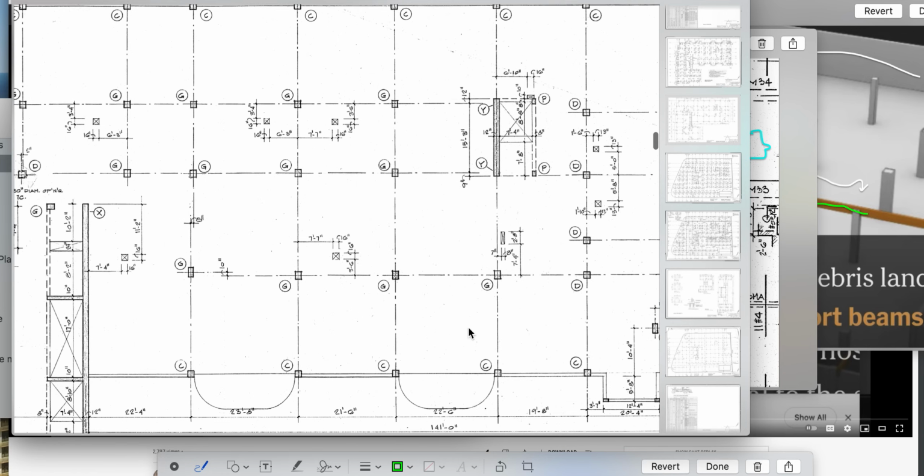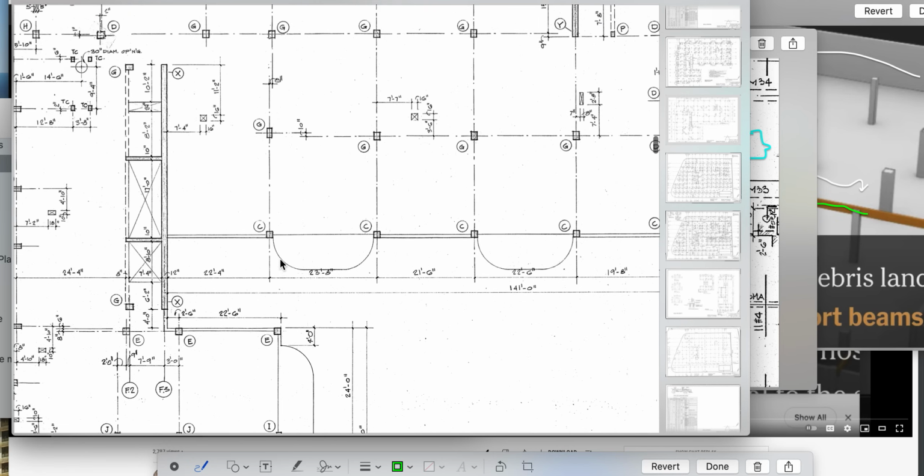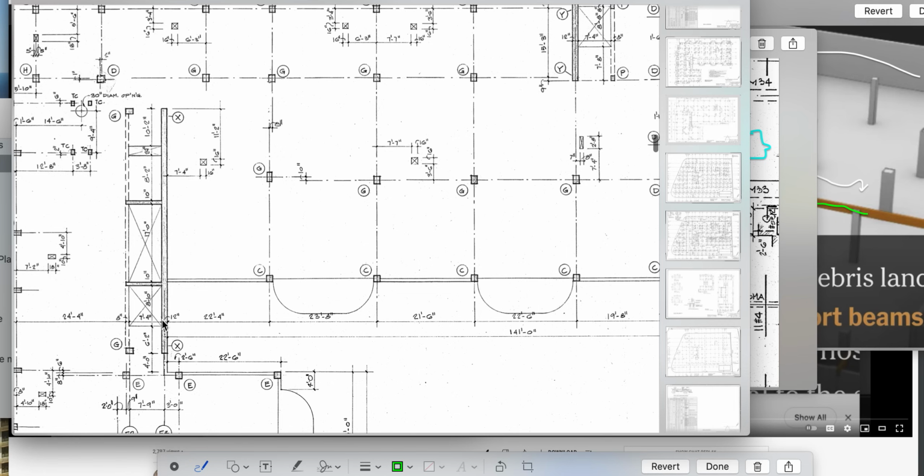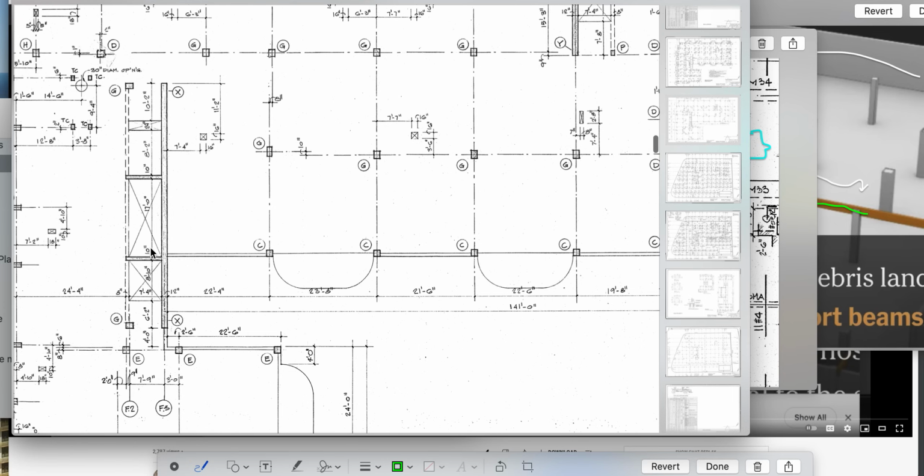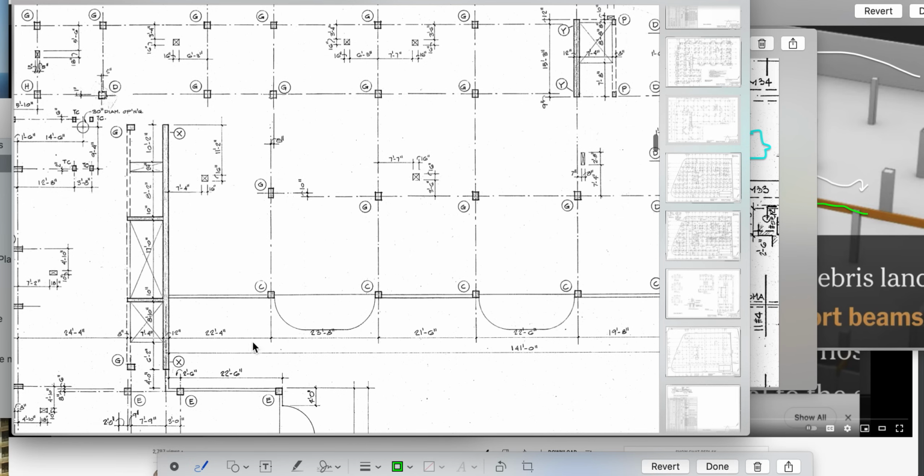M is the shear wall that everyone says doesn't exist. Well, obviously it worked. The problem is the rebar goes across the shear wall via the slabs into the slab next to it. This one worked because there was literally a wall here because the elevators were built up, and so they couldn't go through the elevators. At some point they do go around, and the stairs are here. And then there's an open space here.